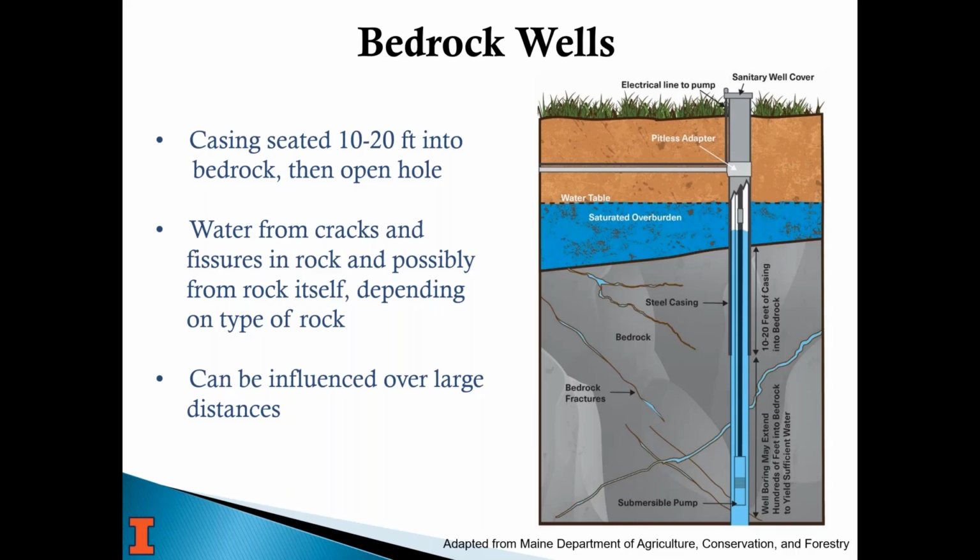Why I said earlier, you need to know if you have a screen. It means typically you'd have a bedrock or a sand and gravel well, not always, but generally. So here's an example of a bedrock well, and this is for a small camp up near Chicago. If you look again at the well log, the geologic log, they hit shale at 257, and so they stopped.